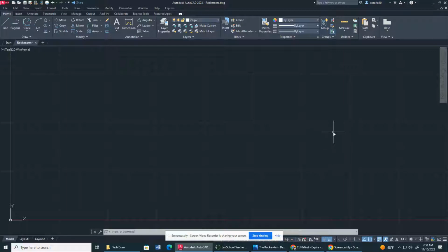Okay. So first, we're going to have to activate the startup option. The startup option allows us to change our screen from inches to metric. Well, not change our screen, but allows us to select inches or metric. Okay. So to do this, I'm going to type in startup, press enter. Now, enter the new value for startup. We're going to press 1, enter. Okay. Now we're going to close out the program.